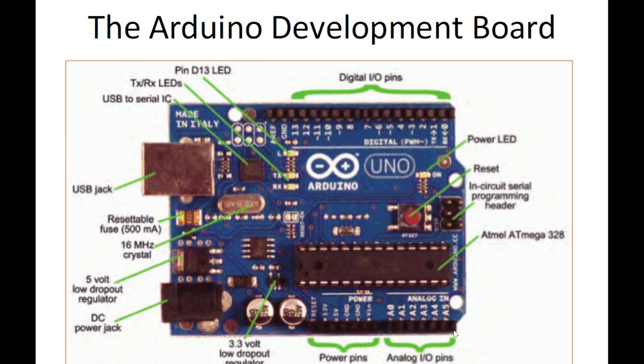These are your analog pins. This is wrong, not I/O. This is only for inputs. You cannot do an output on an Arduino analog pin because I think it doesn't have a DAC. Yes, as far as I recall, it does not have a DAC.